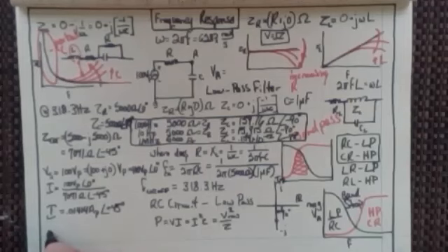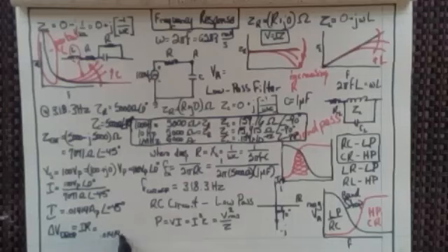So let's just look at the voltage drop. I'm going to write it as a voltage drop. What is the voltage drop across that first resistor? We know what the current is now. We know what the resistance of the resistor is, so we can come up with the voltage drop, because it's just, in this case, IR, isn't it? So for I have 0.01414 amps peak at 45 degrees. There's my current. And then I want to multiply that by the resistance.